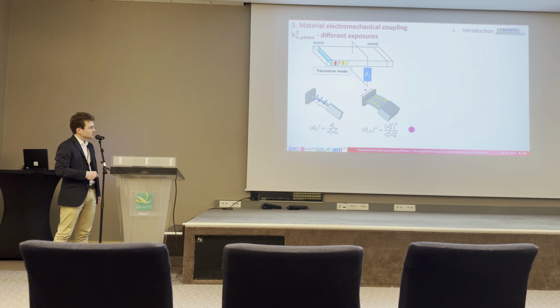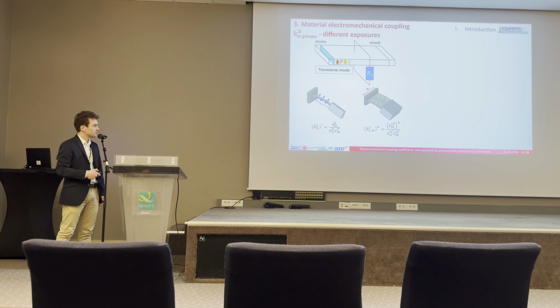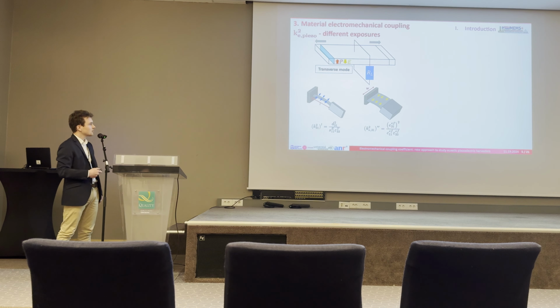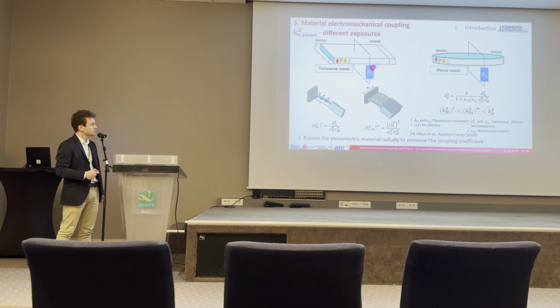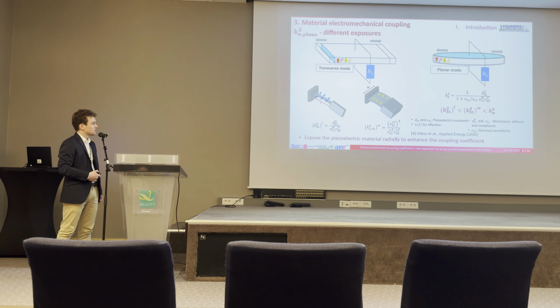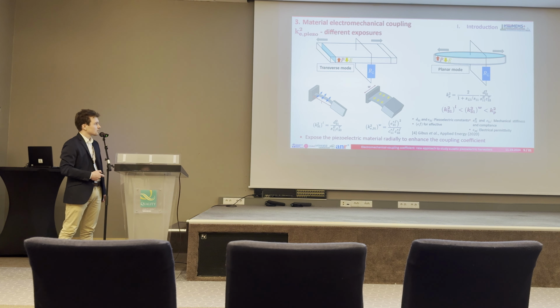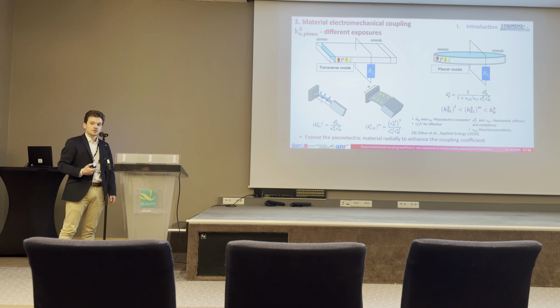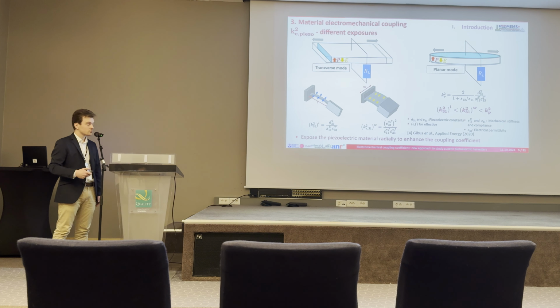For the wide beam, the coupling coefficient is higher because there is no lateral strain in the piezoelectric layers. And to improve this again, we can use the planar mode, which is the same as transverse mode, but omnidirectional. And here again, the coupling coefficient is better than the wide beam hypothesis. So we want to achieve the planar mode exposure, but for this we need some design solutions.